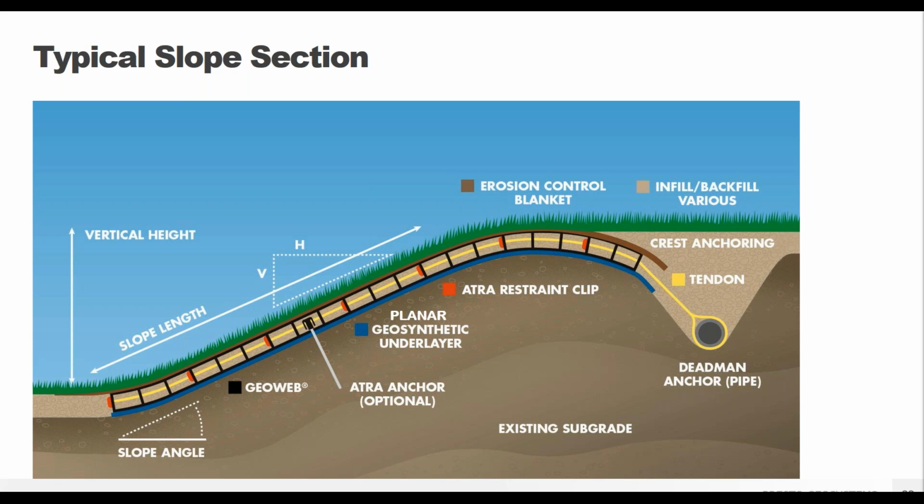It could also be something like an earth or a rock anchor, or you could even bury the GeoWeb underneath a concrete structure. If you know that you have a heavy concrete structure that's there, you could attach it to it or bury it underneath and let the gravity weight of that structure hold the panels in place. So a couple different options. So we can try and find something that's going to be most appropriate for your specific site.